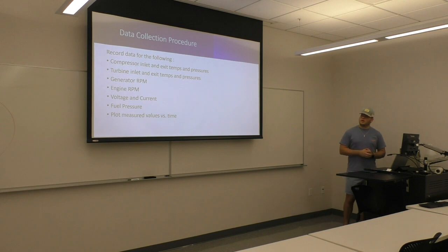You want to record the compressor and turbine inlet and exit temperatures and pressures, the generator's RPM, engine's RPM, the voltage and current, fuel pressure, and you want to plot these measures as a value versus time.